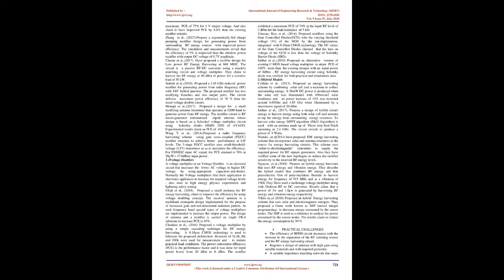3.3 Rectifiers. A rectifier is an electrical device that converts one form of energy, AC, to the other form of energy, DC, which flows in only one direction. Lee et al., 2018, proposed an adjustable impedance matching network with CMOS technology to produce RF energy using 3G/4G cellular low-band signals. The proposed converter consists of a cross-coupled rectifier with differential drive and a 4-bit capacitor array. The RF-DC rectification has a varying conversion efficiency with different loads.